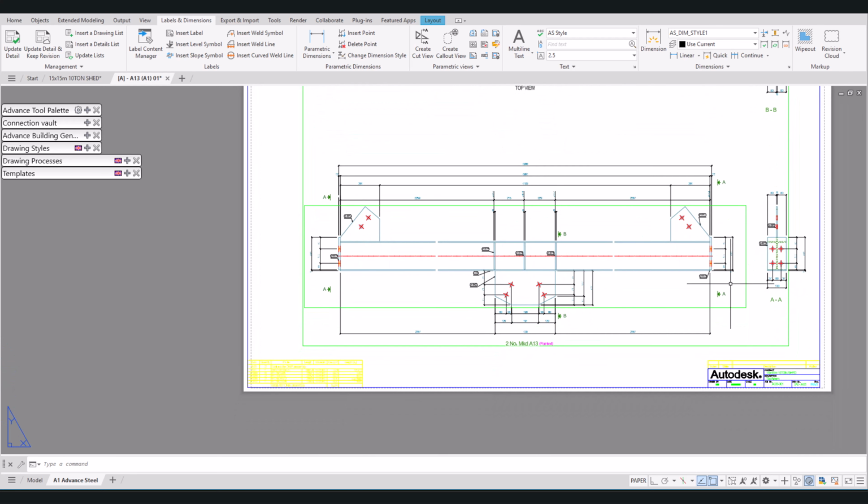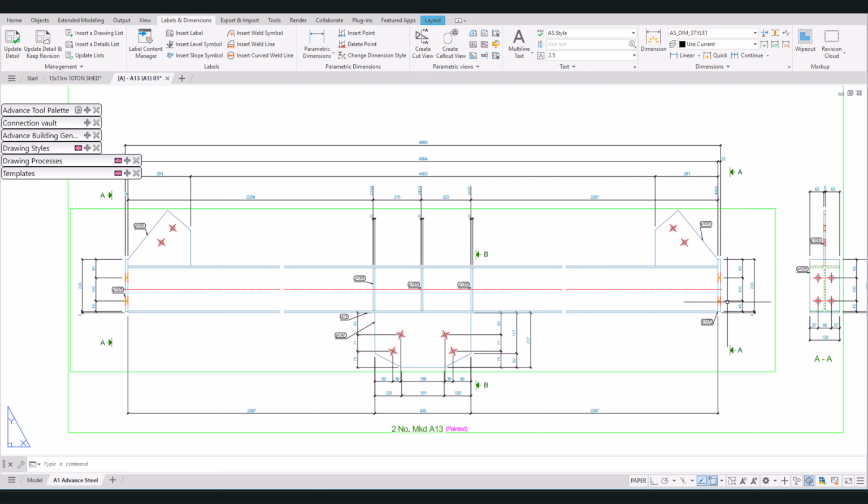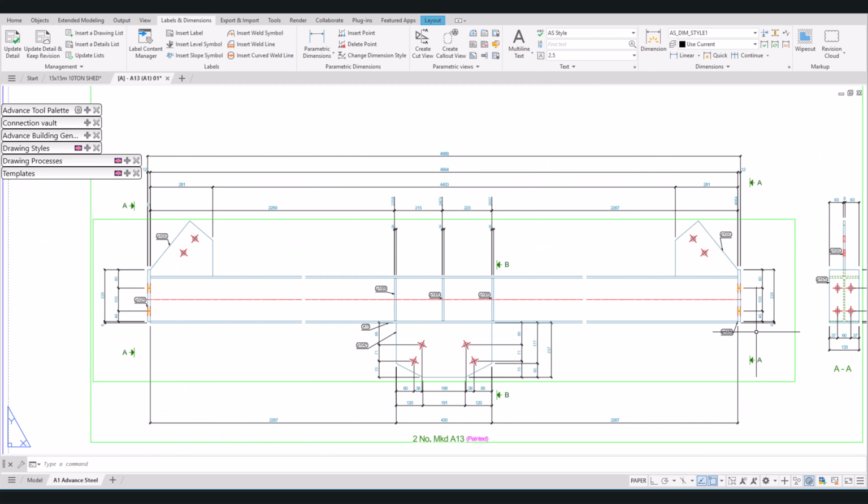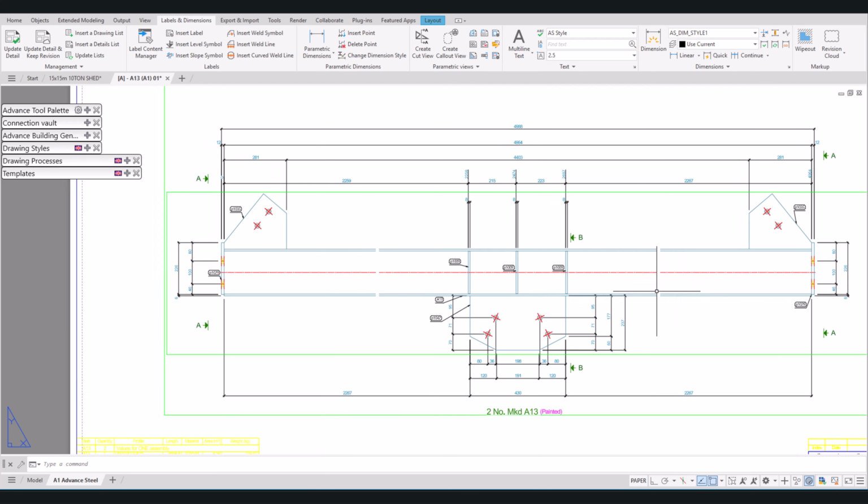Make sure that when a boilermaker receives a drawing like this, they can easily follow that, okay, to place this end plate, we need to measure 6 mil from the bottom of the beam, and the 46 mil side of the plate is the one that's at the bottom. They need to see all those dimensions, and it has to be clear so that you don't cause confusion and downtime when the boilermaker has to constantly come to your office and check with you.